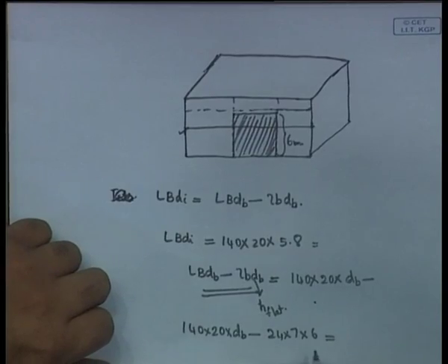But you can easily see 5.8 to 6 meters, you will definitely go above that. So, that is why we have directly assumed that it does go above that, otherwise yes, you are right. Then you might end up getting dB as negative or something. You will have to do that and see, if you assume that it is below, you might get dB negative, which means that it has actually gone above the flat, that it will not match, you will not be able to solve it.